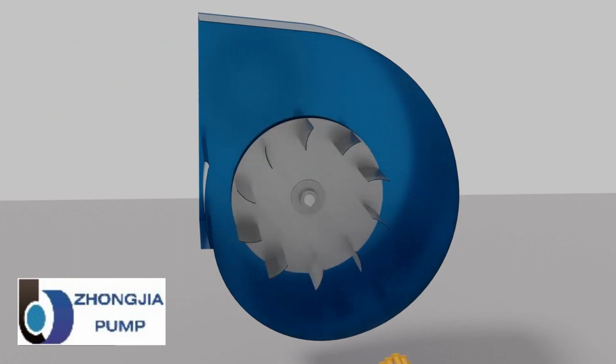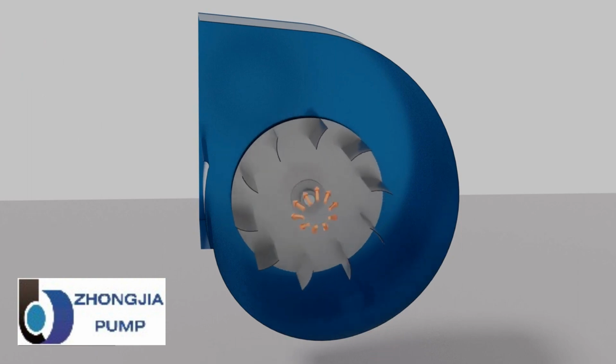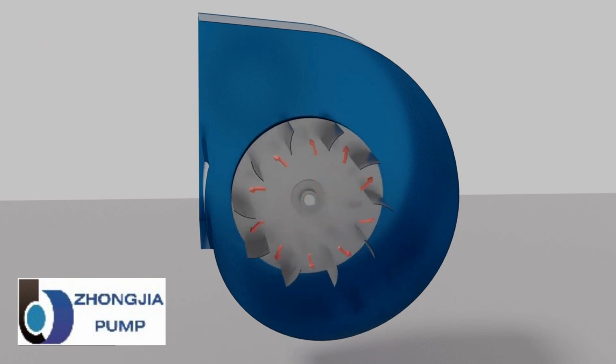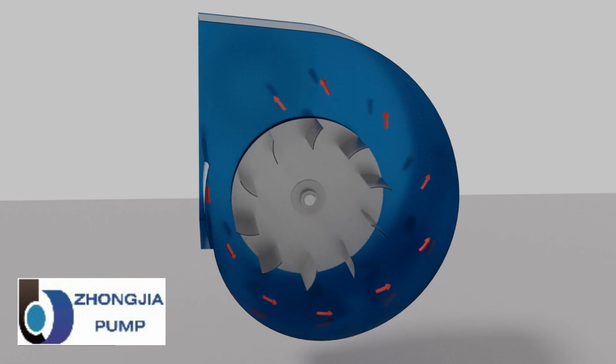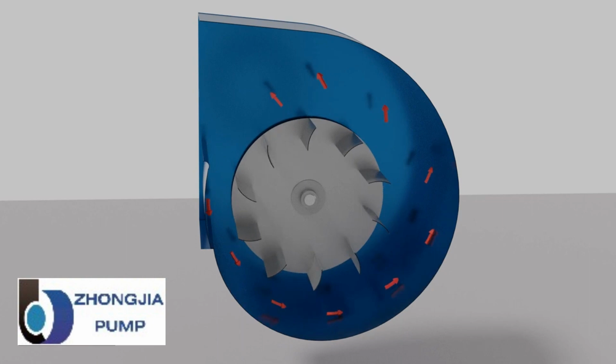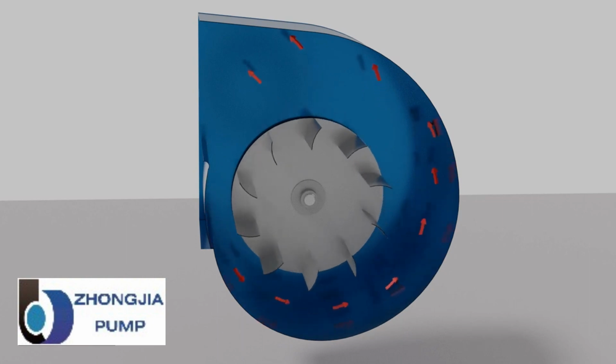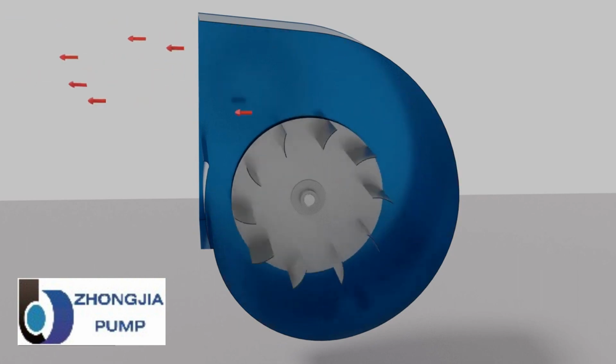If we look closer, we can see that first the air is being pushed outwards, and then it's deflected by the impellers. Then air moves in a spiral direction. Both effects will increase its static pressure and velocity pressure. When the air reaches the casing, air gets slowed down a little, which increases the static pressure at the expense of the reduced velocity pressure.